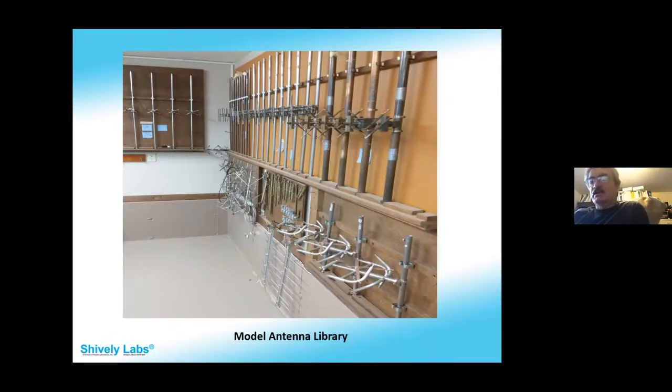But especially even at UHF frequencies, the criteria for an elevated range is to keep the main beam of the source antenna off of the reflecting surface, and that's really hard to do at UHF. You can get a ground reflection range, and maybe that's what you're doing. I couldn't tell from your photographs. It looked like an elevated range. And then what you do is you adjust the height of the source antenna so that the reflected signal and the main beam are in phase alignment with each other. It kind of contaminates CP if you're trying to get CP measurements. That's another issue. There's a couple of other things you can do. You can use diffraction fences and longitudinal wrap, things like that, to try and reflect the ground reflections away. But that looks like a big concern.